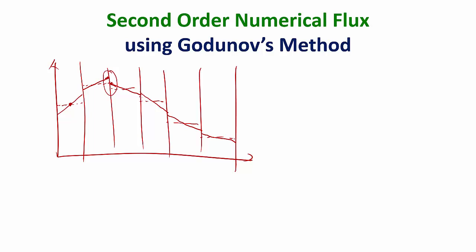And previously, we had a question that we don't want to take information across the shockwave, right? And if we treat every interface as a potential shockwave, then we want to use only the left of the discontinuity to reconstruct this value, and only the right of the discontinuity to reconstruct that value.